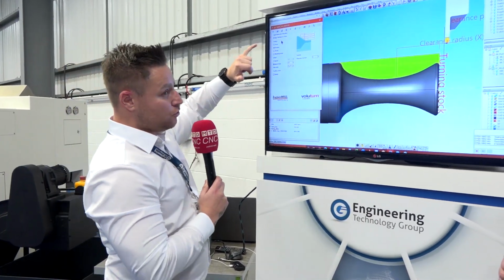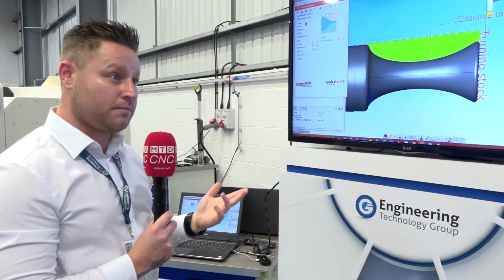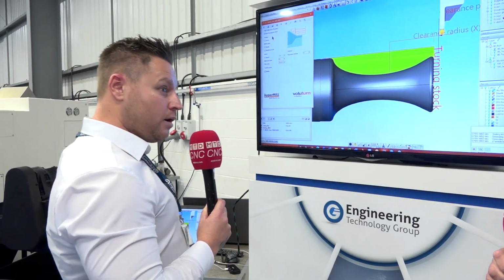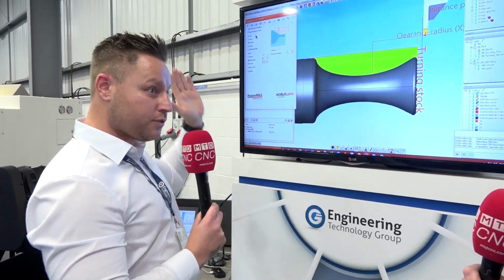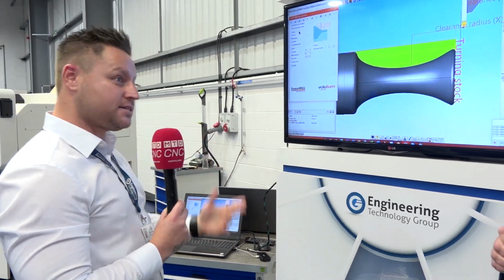When you change it over to a ramping, which is an extra area that we've got on top of our Max Turn environment, what it's doing now is it will do a feed towards the chuck, and if you have a tailstock support on here, the feed will now also reverse feed. So now you have a constant cut. So what's happening now, the tool stays in inclination at all times with the ramping. So you are now taking your tool path to the next level in the Max Turn environment.